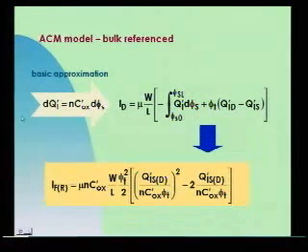By applying this basic approximation to the differential form of the drain current and integrating afterwards, we have the two saturation components as functions only of the inversion charge densities. Okay? Now I have to relate the inversion charge densities to the terminal voltages, to the voltages VGB and VCB.